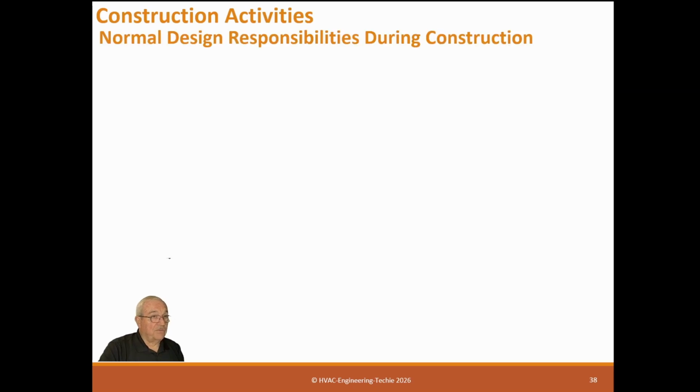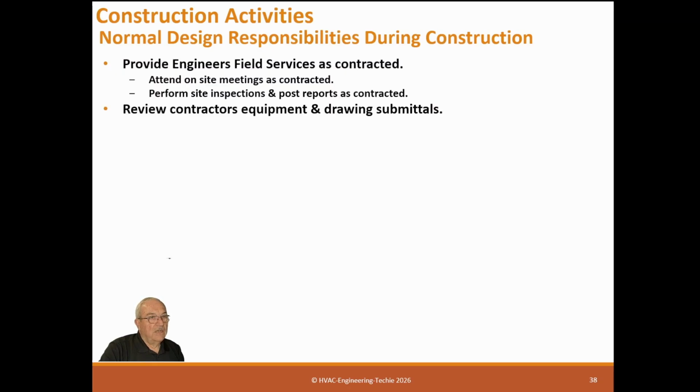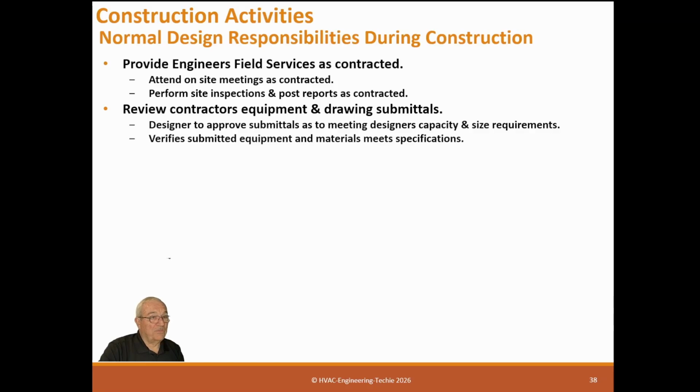Design activities during construction, as long as you have service requirements. Provide engineering field services as contracted, attend on-site meetings, perform site inspection and post reports as contracted, review contractors' equipment and drawing submittals. The designer approves submittals as meeting design capacity and size requirements. Some people say they don't approve them anymore, they just say reviewed, fine. But what it means is, whether they like it or not, they've approved it.